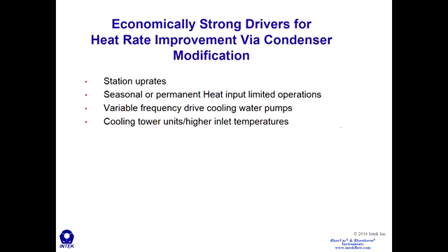And some economically strong drivers for heat rate improvement via condenser modification. If your station is looking to uprate, if there are seasonal or permanent heat input limited operations, then a retrofit will not just decrease the unit heat rate, it will actually increase total generation of the unit.